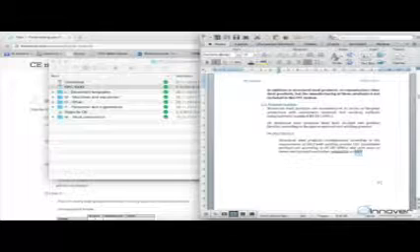And here we define the hardest steel, the one with the lowest weldability, that is going to be included here. So basically MAG welding and steel S355 or better weldability. So MAG welding and S355 or lower, structural steel, or lower mechanical properties like S235.